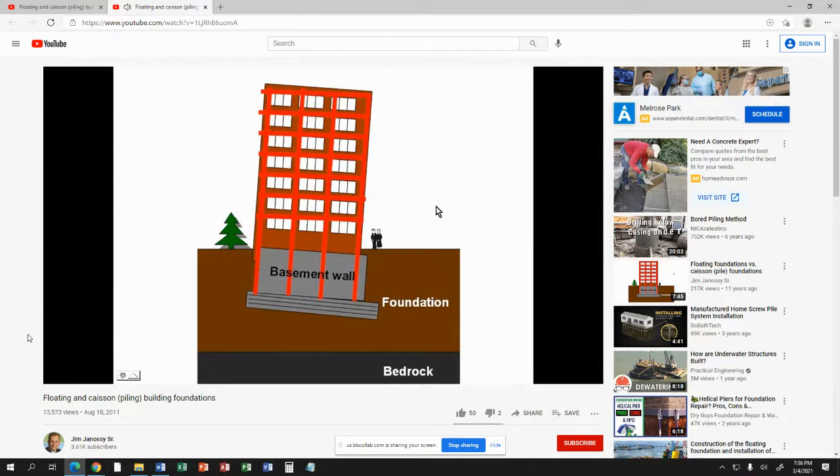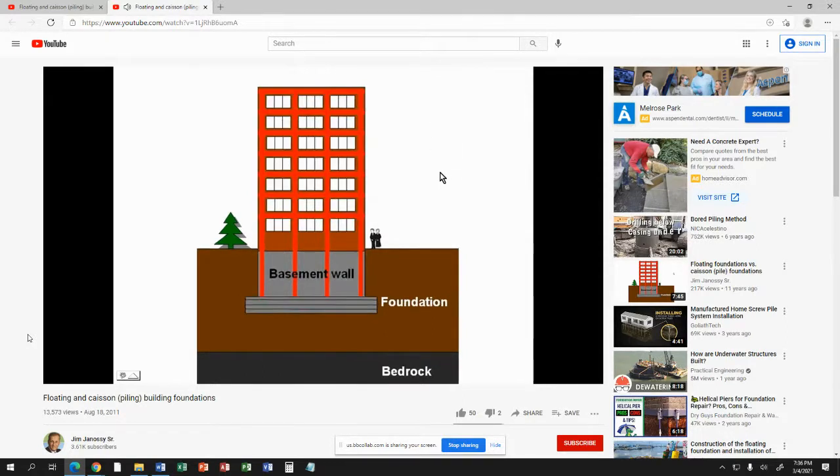Many of the old structures are now taken down because the land became more valuable than the rents that could be earned in such a small leaning structure, and it was eventually demolished. Something better had to be done. Well, let's take a look at a building that had properly settled. Let's suppose it were constructed instead using a caisson foundation or some type of pilings that actually reach down to the bedrock. The bedrock is solid.